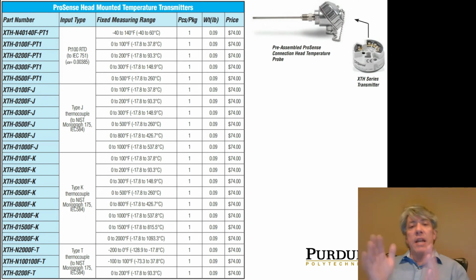So you're going to get nice resolution but a low range. On the other end of the spectrum, say 0 to 2,000 degrees, again taking 2 to the 12th as our analog to digital converter, so we've got 4,096 different levels we can measure, and then 2,000 divided by 4,096 comes out to almost 0.5, but 0.49 or so. So the smallest temperature change we can measure or detect would be 0.49 degrees. So we're trading off resolution for range in that case, see.